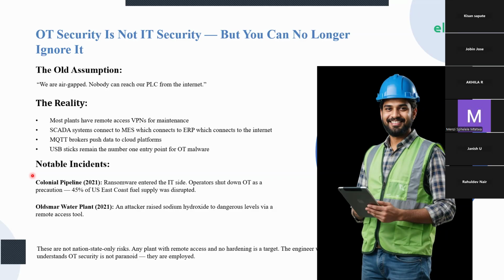Like we discussed with the OPC UA, MQTT and Modbus TCP communication methods, Modbus TCP is considered an open communication because it can be read by anyone in the network. But when it comes to OPC UA and MQTT, there is a standardized way of securing the communication. It is actually a basic of cybersecurity, because we are just encrypting the data between two devices so that a third party cannot understand it or access or control the device we are communicating with. That is a very basic level of security everyone can understand.